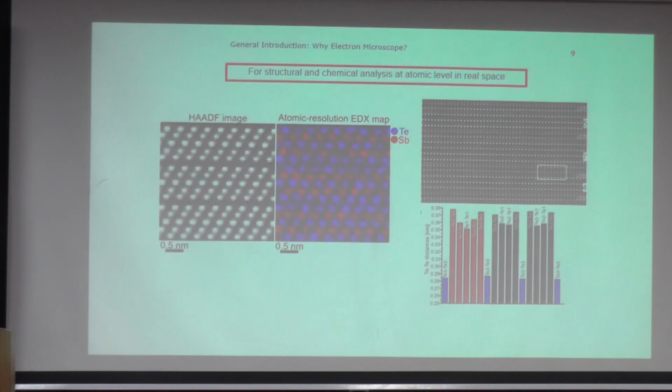And of course we can also use TEM for quantitative analysis, like the spacing in the crystal lattice, if you want to study some relaxation in the lattice, some strains, or some real features like distances between these so-called vacancy layers or van der Waals gaps.